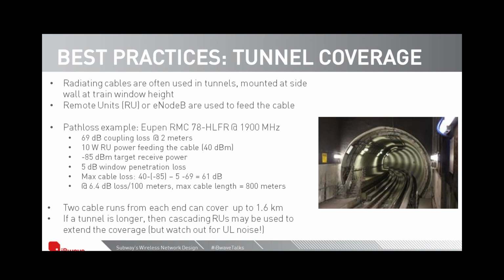And if we assume that we are feeding this cable with an RU that has 40 dBm power, and if we assume negative 5 dBm target receive power, and if we assume 5 dB window penetration loss, and this figure actually was obtained from literature, then the maximum cable loss is about 61 dB.